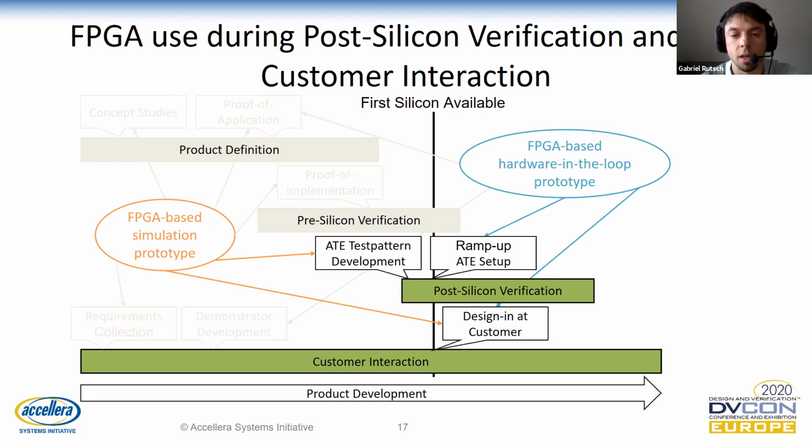There might be some stray fields, or there might be a different geometry of the wheel, or the orientation of the sensor is different. This means that you need to run the whole pre-silicon verification test suite again with some different parameter settings. On the other hand, it also allows the customer to use the FPGA-based prototype to define or develop his own ECU early on.